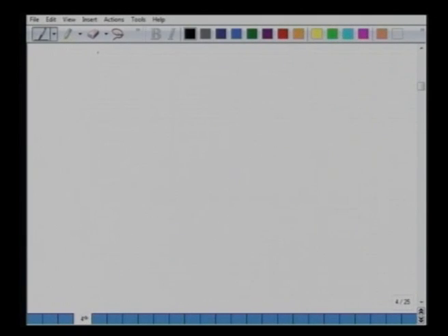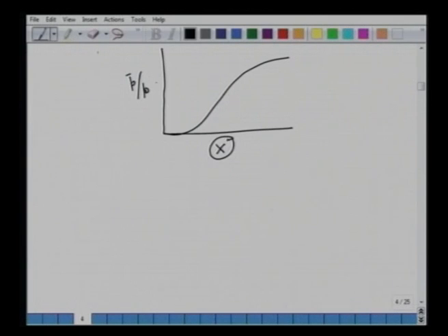We also had drying, the last unit operation. There also we have a very similar curve like this. Moisture content in equilibrium as a function of saturation humidity or relative humidity, relative saturation. So partial pressure of the gas, non-dimensionalized with respect to the partial pressure of pure moisture at a certain temperature. So here we said we have different regions for a given quality of this air; moisture in a certain solid cannot go below this. So this is your x star. So here we had this unbound moisture and the bound moisture, etc.